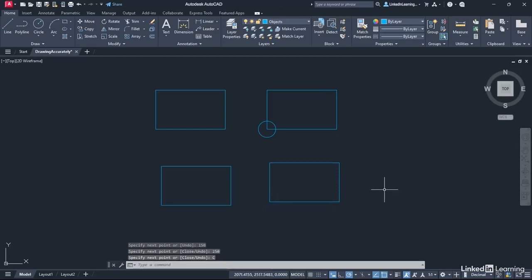That's the quickest method of drawing in AutoCAD. Utilizing the polar tracking, utilizing the direct distance entry, and combining that with the dynamic input. So top left rectangle took quite a long time. Top right rectangle, little less time. Bottom left rectangle, even less time. And then the quickest is dynamic input, direct distance entry with polar tracking switched on. You can see how quick that was. I don't even have to click on that second point of the line. I just press enter to confirm the distance.